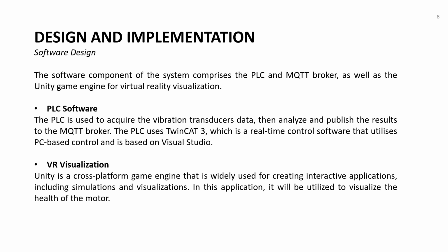TwinCat3 Analytics Workbench, which is a graphical user interface, is used to create and deploy data analysis programs. The condition monitoring library in TwinCat3 is also utilized for the vibration assessment. The PLC program is then triggered by the MQTT parameters and the start signal which it will get from the VR application. After it will start doing the real-time analysis and publish the results back to the VR application.